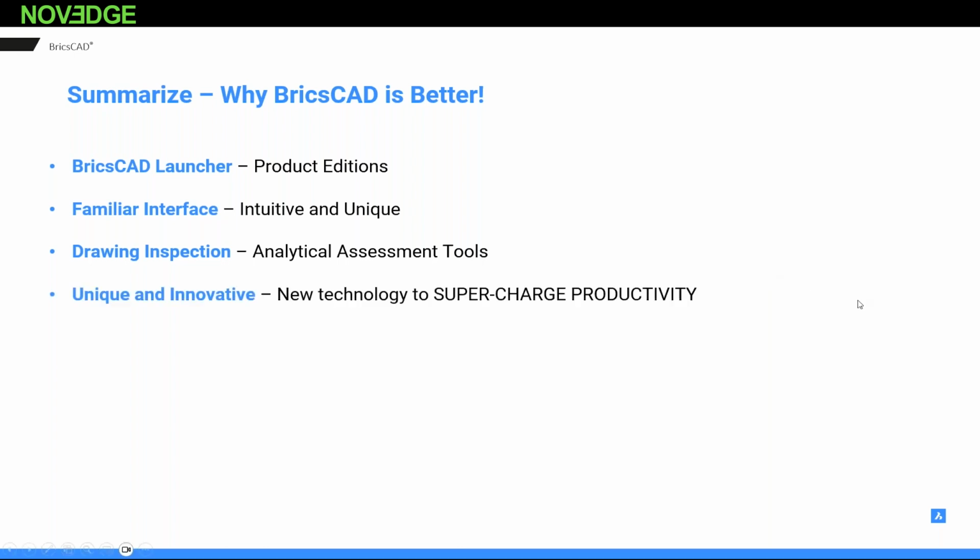I also introduced you to some of BricsCAD's new technology to increase productivity, such as move guided, copy guided, the quad, rollover tips, manipulator, blockify. I covered how you can display various design options using parametric blocks and how you can continue to utilize existing dynamic blocks in your workflow.